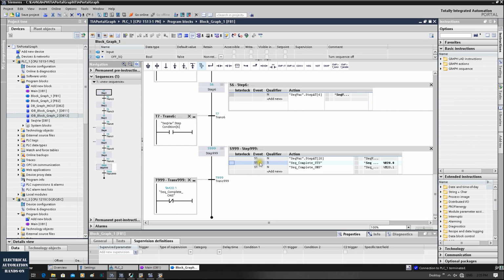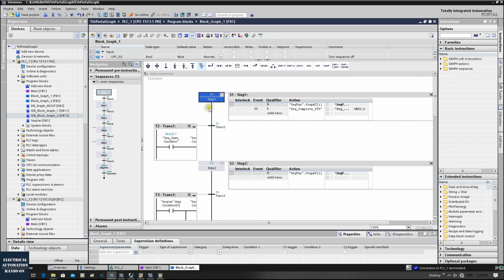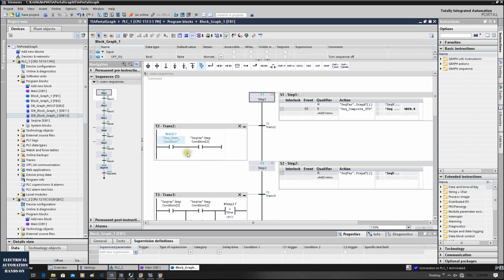And keep in mind, because I set this command here, when we jump out of the first step, I will use S0 to reset this flag signal. S0 means outcoming step. That means by default, this step will be held here, waiting for these conditions, and then jump to the next step. Basically, at that moment, this sequence starts working.